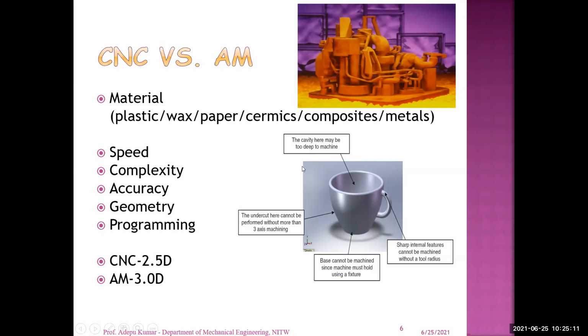Then while machining, what we observed is there are many more irregularities. The surface finish you are getting through the milling process is not equal to your requirement. Then I realize that this process is not suitable for ceramic materials, because ceramic is a very hard material that comes under the brittle category. Even when you remove the material, the removal is not in a continuous form. It is discontinuous in nature. That's why you are getting unevenness or more surface roughness. That reduces the quality of the component generated through the milling process. So my success rate is very, very low.